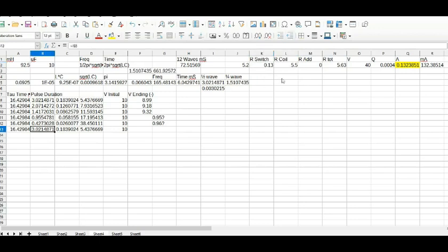So now we can think about a few more things. If we have the resistance and the inductance, then we know the tau time of the coil, right? Because the tau time is inductance over resistance. And you see that's constant. It's independent of the cap that we use. Now what does the tau time of the coil tell us? It tells us that in 1 tau time, under a situation of constant voltage, the magnetic field strength of your coil will reach 63% of its maximum.